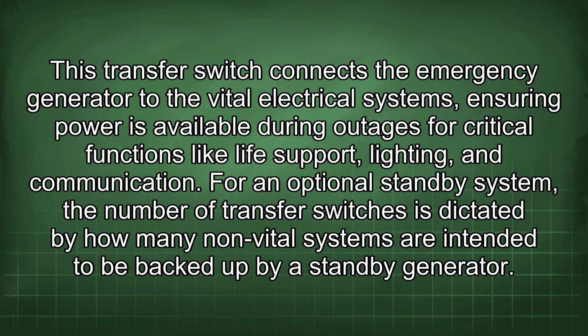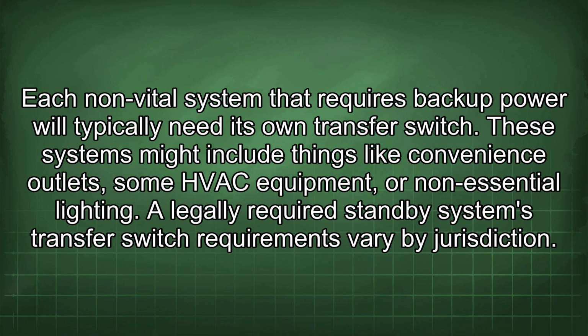For an optional standby system, the number of transfer switches is dictated by how many non-vital systems are intended to be backed up by a standby generator. Each non-vital system that requires backup power will typically need its own transfer switch. These systems might include things like convenience outlets, some HVAC equipment, or non-essential lighting.